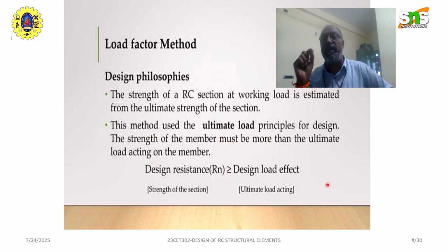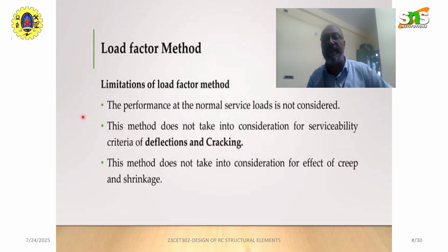In this method, the ultimate design strength principle is used. The load factor method does not include deflection and cracking, which is a limitation. It also does not consider creep and shrinkage, which we already studied in concrete technology. That is the limitation.